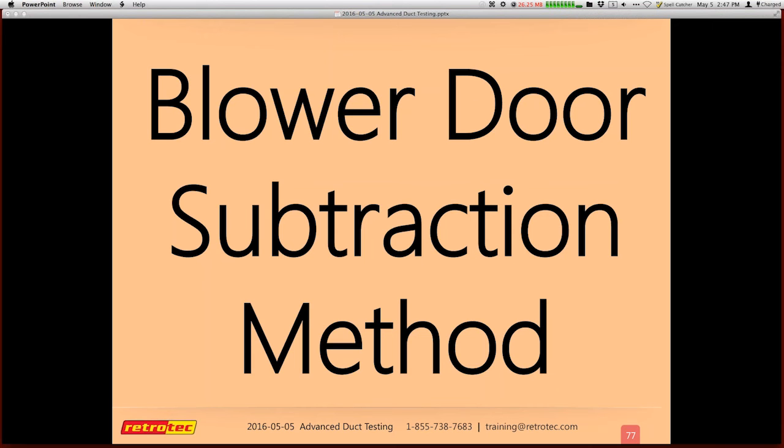So in general, you're going to be doing the blower door test for leakage to outside. But if I'm just going to do a duct test, one of the things that some people do is they will only pressurize a duct system because they are concerned that if they do depressurization, they may be bringing contaminants into the house. And those are the kind of things that come from experience, for somebody who's doing a lot of these, or in the house, gets a feeling about what kind of exposure I might be having with how old the system is or how old the ducts are. Taking off a couple of registers will give you an indication about what type of maintenance they've had, if any. Hopefully that helps them. Any other questions we should catch on?